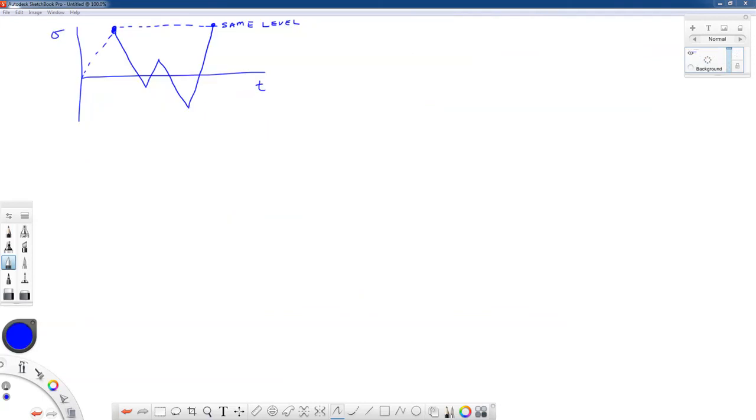So let's take a look at what happens with a very simple variable amplitude loading history. So again, I have stress versus time here, and I'm going to plot the hysteresis response for the material, assuming that we have a little bit of plasticity. Now, I'm doing this as a sketch, but the sketch is good enough to identify these closed hysteresis loops. So over on this panel, I'm going to have my sigma and my epsilon, my stress versus strain.